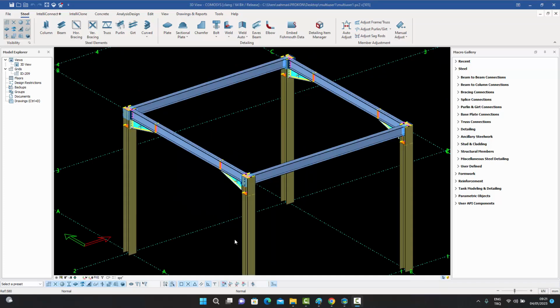So here, for instance, what I did was I added the 4 connections in the user 1 model and uploaded my 4 connections, the haunch connections which you're seeing on the screen, to the server. And now I've opened the desktop, the user 2 model. The user 2 model is now open, and I just downloaded from the server, and I have managed to download the 4 connections, as you can see on the screen.